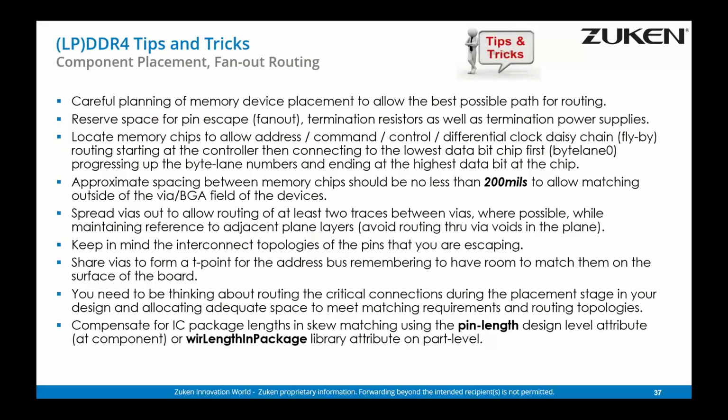Take into account proper spacings, then you have to route into the BGAs, do a proper planning of the wires, because if you have differential pairs, you must route the two legs of the differential pair through the wire field. Otherwise, you make a general design rule mistake if you spread the differential pairs apart.